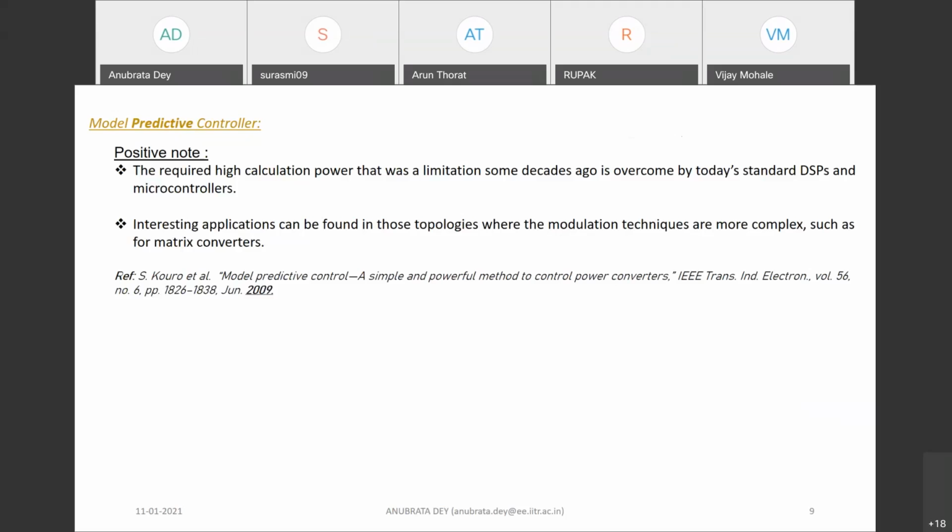In a multi-level inverter there are many states. For example, a three-level inverter has a zero state in between plus and minus. How current will behave during that zero state is a little different from the two-level inverter. So probably you need to use a multi-band or multi-layered band instead of a single band, and this will become more complex as the number of levels increases. In a five-level inverter, the complexity will increase immensely. On top of that, there will be stability issues during transient conditions.